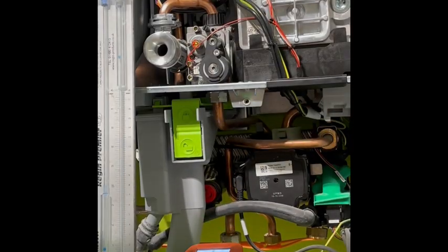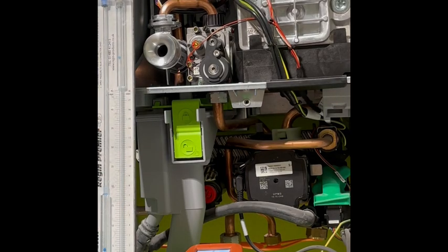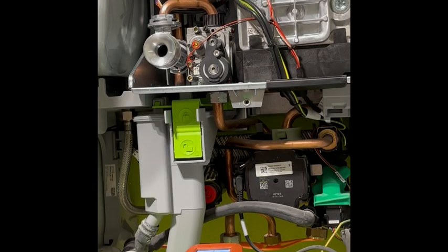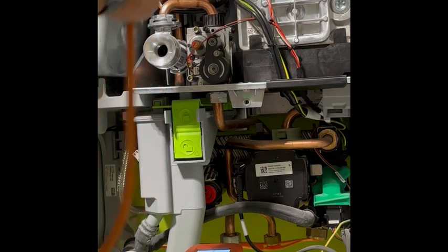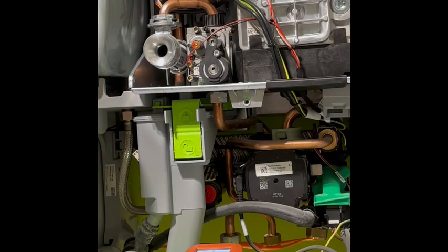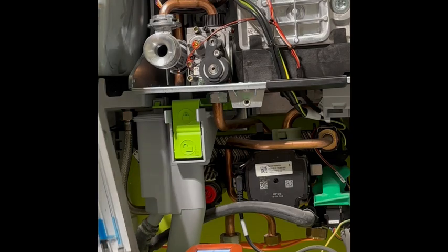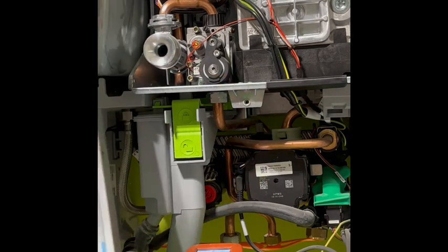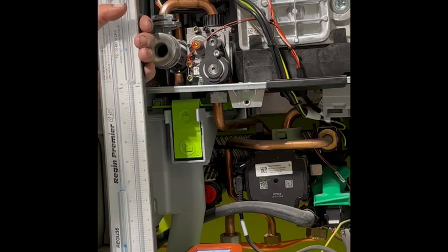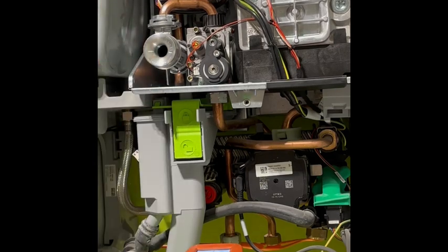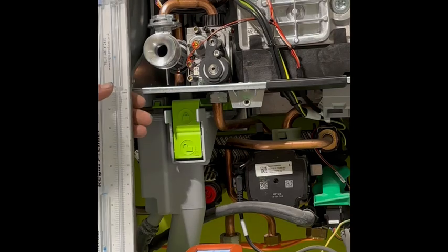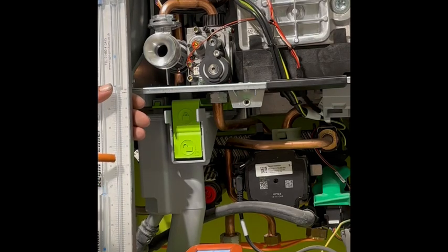So the reason I like using one of these is because if you're going through an ignition sequence and you've only got, say, a 5 to 10 second window of spark and gas being drawn into the burner, if you're waiting for that analyzer to settle and drop down in digits, you can miss it sometimes. So this is almost instant, it drops to where you need it to be. Another thing to be aware of is these gas valves generally open quite quick, so you'll notice a movement on the gauge quite quick.